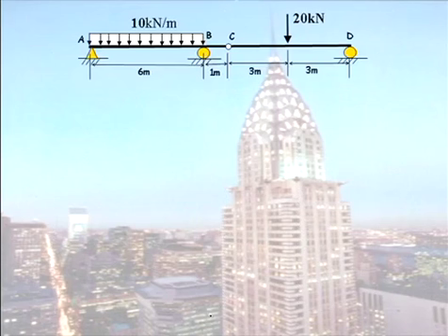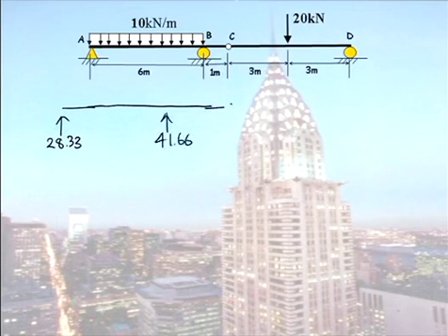What I'm going to draw now is my free body diagram of the left-hand side with my known reactions now, because that was the first thing we needed to do. Now, when I cut this beam, I'm trying to come up with one equation valid for the entire beam.